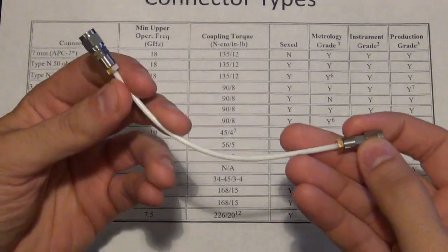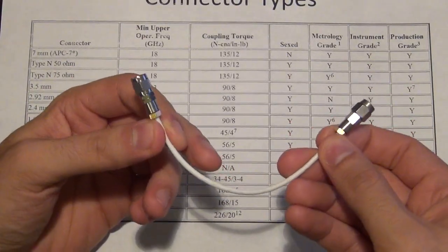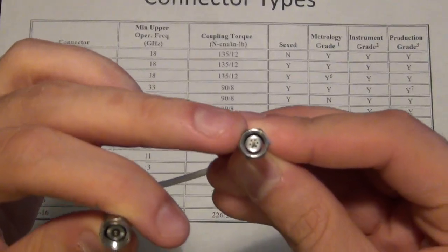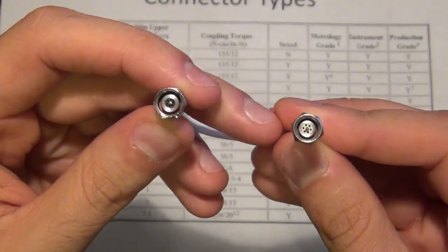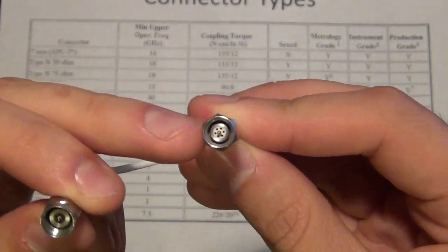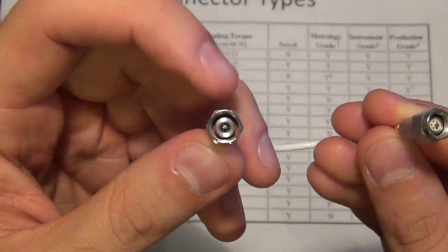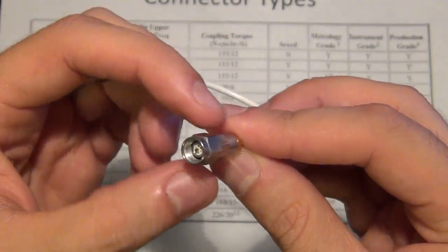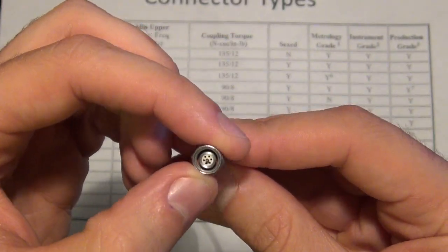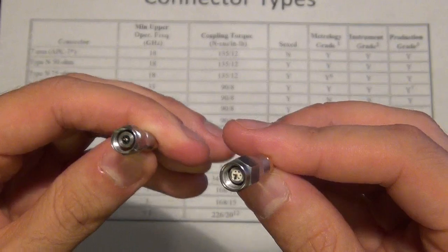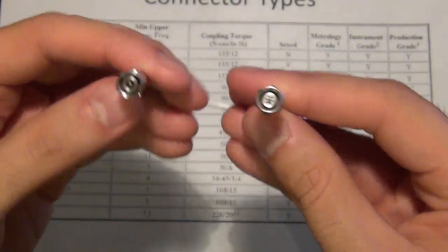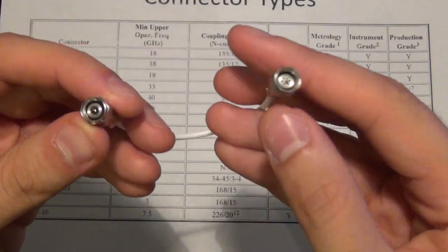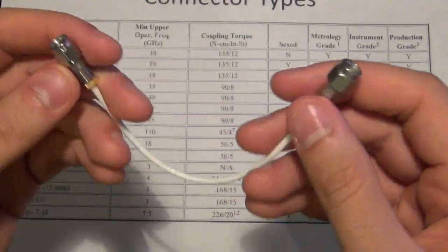Sometimes it's also possible to get cables that do conversions of different types of connectors for you. So this cable actually converts a K, which is this one, to a V. Now you can see right away that the dielectric of this one, which is the white one, is much wider than the dielectric of this, which is the black one. This doesn't use an air dielectric, or not completely air, because the dielectric has some tiny holes in it, but it's not just air essentially. So be careful when you pick up a cable. Examine the center tab. Make sure you know what type of connector this is.